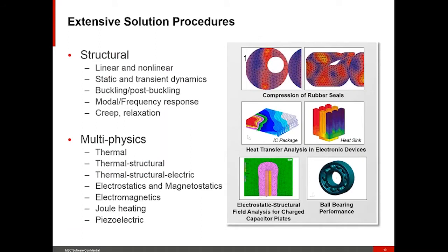For structural analysis, the user can use Marc to conduct static and dynamic analysis. Time-dependent effects such as creep and relaxation can also be included. Marc is also a multiphysics code. The user can run multiphysics simulations such as thermal structural coupled analysis.